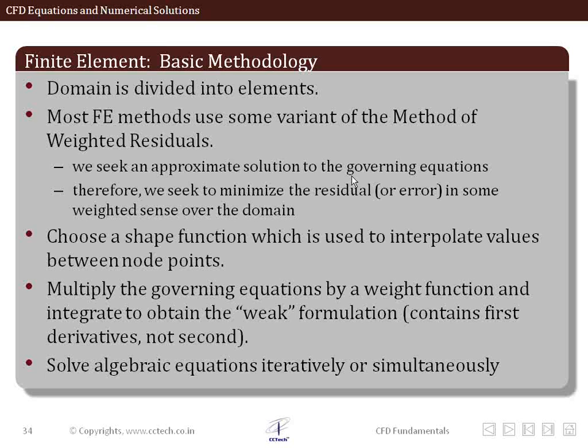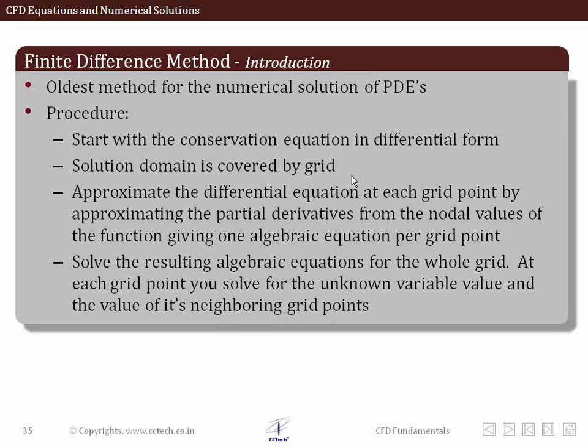But in all these three cases, what we end up doing is we convert the partial differential equations into linear algebraic equations, which are then solved simultaneously to obtain the solutions. We'll see this example more specifically for the finite difference method now. The finite difference method is actually trying to obtain a numerical solution of partial differential equations. We start with the conservation equation, but as was mentioned earlier, it's in the differential form, so it assumes that your quantities are continuous and differentiable, which may not be the case for shock waves. So therefore shocks cannot be captured using the finite difference method, because it is based on the differential form of the equations. We require the geometry to be discretized.